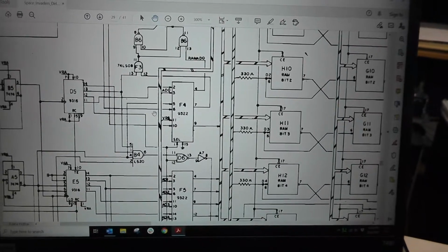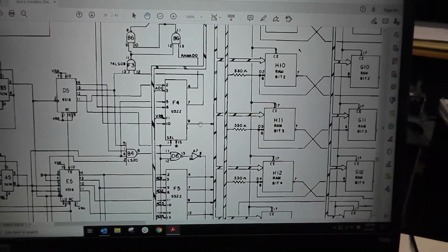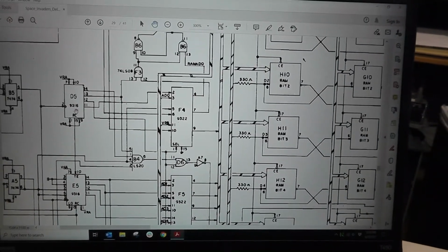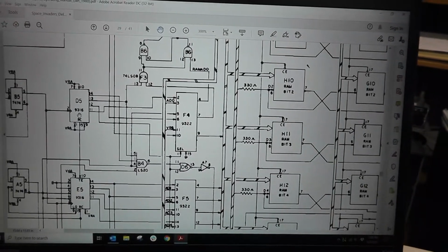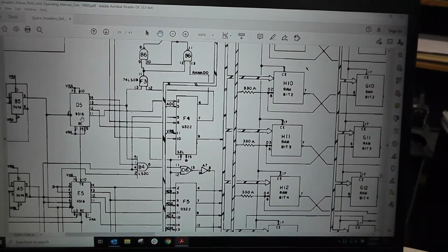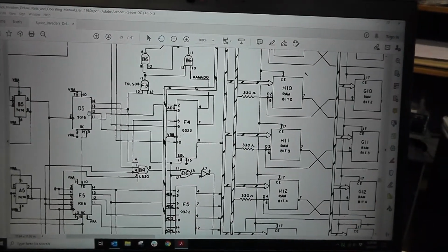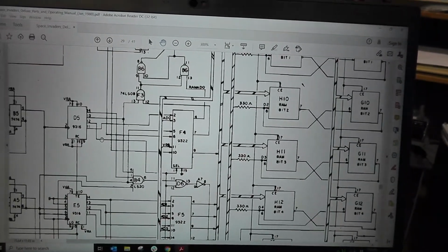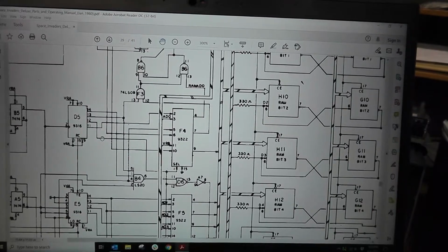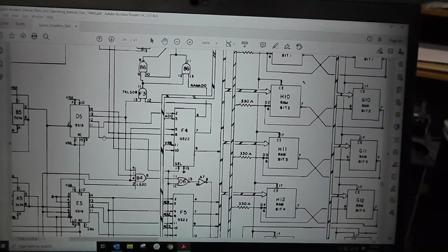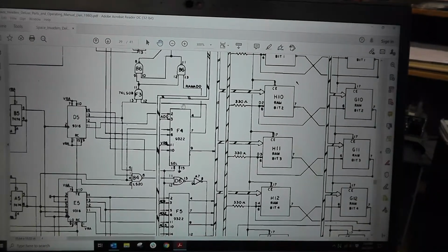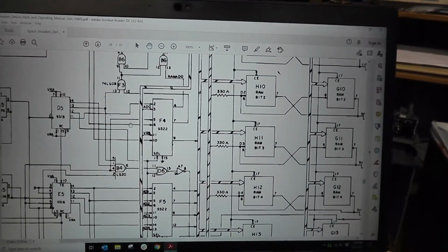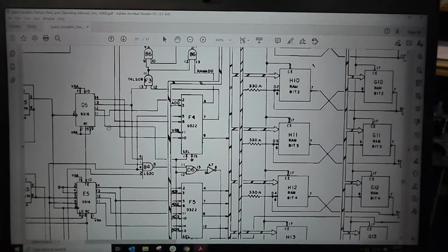Basically, you have your address bus that goes into the RAM. Here's your RAM over here on the right hand side. And you have your timers, which are your 9316s, or whatever we replaced them with. The timing circuits do a lot besides generate 60 hertz and 15k horizontal hertz. They also set enable pins and do addressing of the RAMs, and that's why I like to call it the video address bus, but I think I got that from Williams or somebody else.